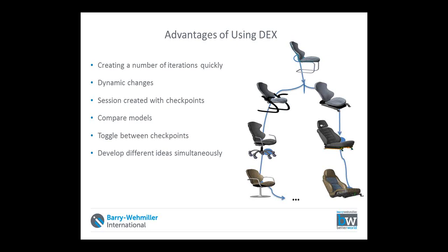The system replaces in session for you the different model iterations as they were when you created a checkpoint. So you do not need to clear session or change your working environment and manually change versions or locations. The system automatically switches all model iterations for you as they were stored in the active checkpoint. And once we are happy with the design, we can accept this particular checkpoint, and only then are all the changes that we have accepted applied to our original models. So guys, let's head on to our demonstration for now.